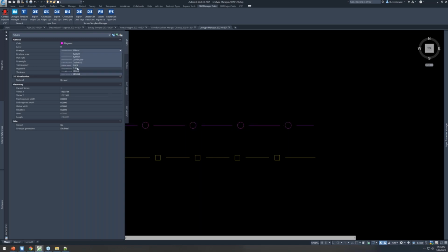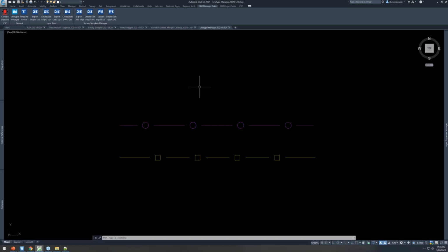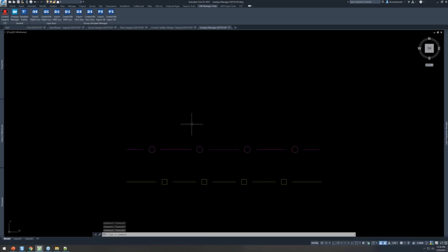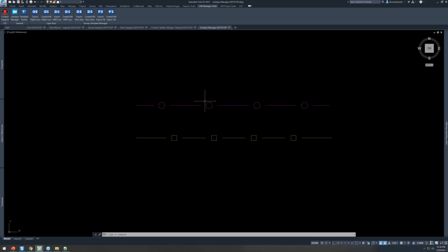What about the reverse of that, okay? If I've got geometry in the drawing, I've got line types in the drawing that aren't in my lin file, it's a common thing. Old lin files get lost, right? The line type definition can hang out in the template, but say you're trying to update or clean up your line types after a few years, and you're trying to get them all into one lin file, you often need to read those line types from an existing drawing or an existing template.